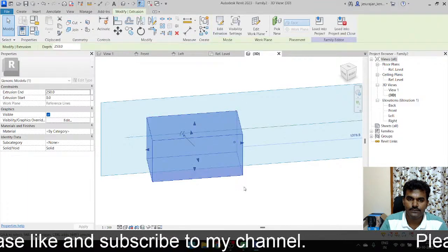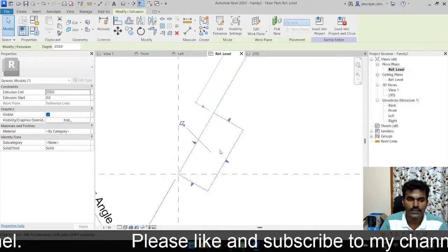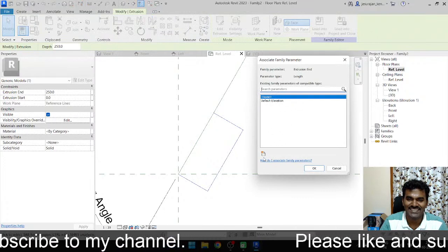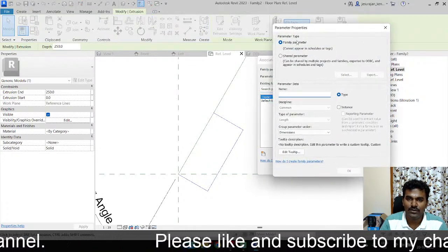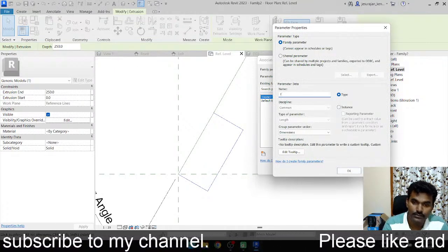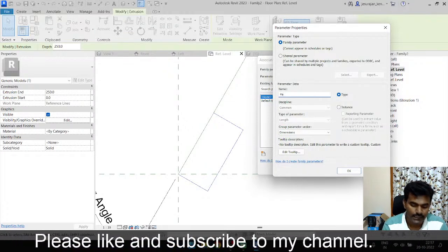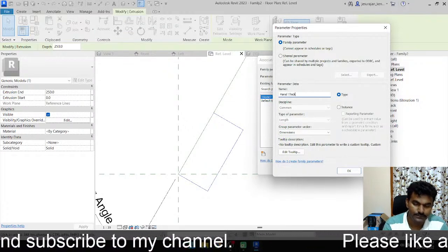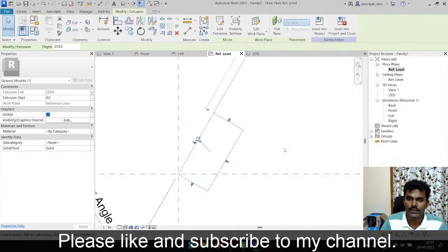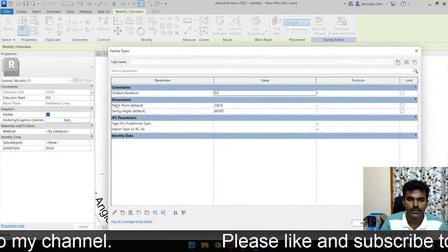Okay, finish. So I'm going to the reference level. This is a very important concept. Everything is important, but it's a very important concept. Go to family. Here I'm going to select panel thick. Keep this as instance. And what's the thickness? Here we have to write panel thick.